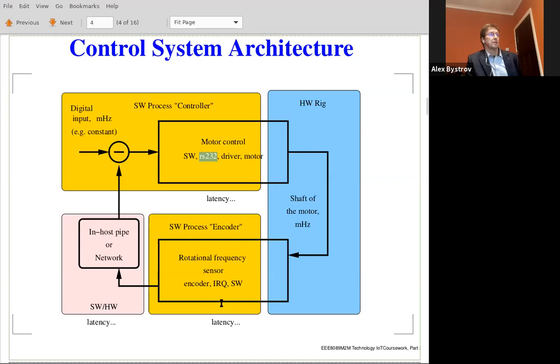There, the source of latency is on this side. What is the source? When we are sending pulses here, there is a counter which measures the number of pulses coming from the encoder within a measured interval of time. If it is 20 milliseconds, then 20 milliseconds of accumulation time gives us around half of that, 10 milliseconds of lag. So 10 milliseconds of lag is here, and also the program itself gives us a fraction of a millisecond latency. So the latency accumulates, you see, accumulates. Then there will be a latency here.